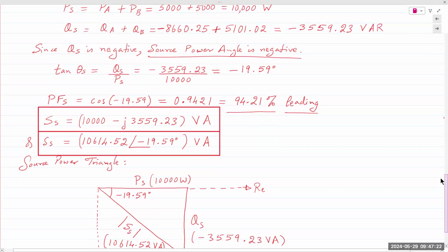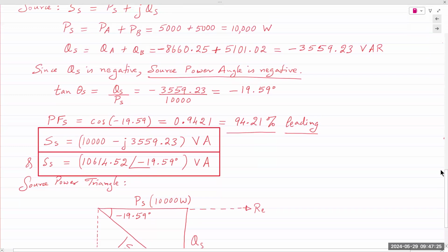The total power factor for the entire system, minus 19. Okay, meaning the capacitor actually is providing a lot more energy than the inductor requires. It's going negative. Remember, QL points straight up, QC points straight down. So if QC is larger than QL, then your angle, instead of being positive, is now going negative. The capacitor is actually delivering more power than is required. So it's the other way around. Capacitor actually absorbs more energy from the source in steady state.